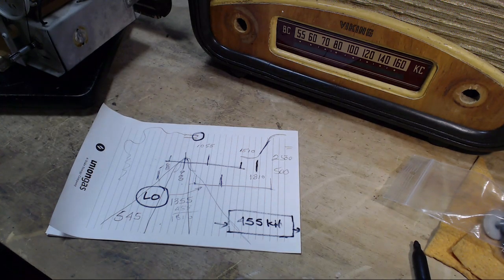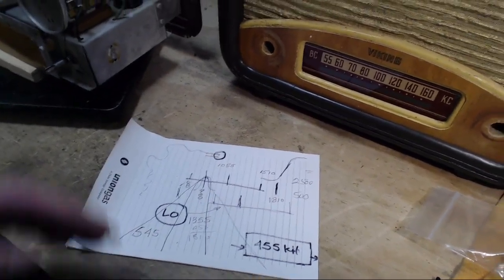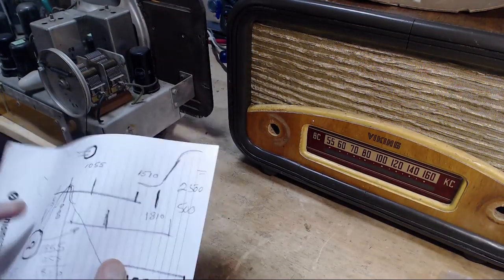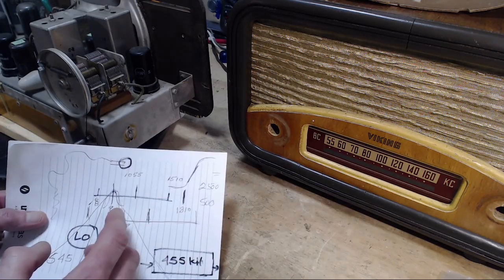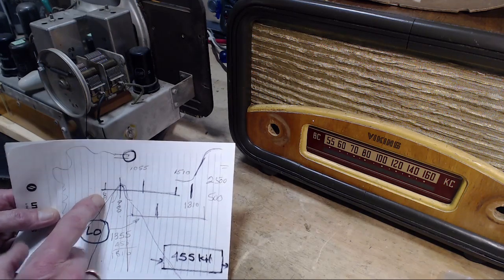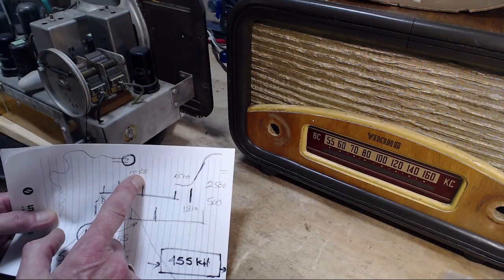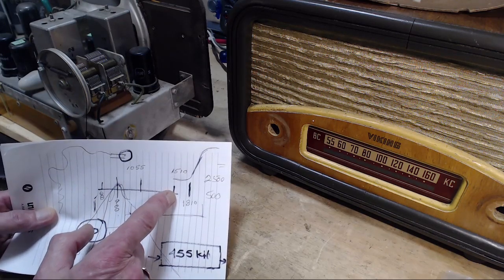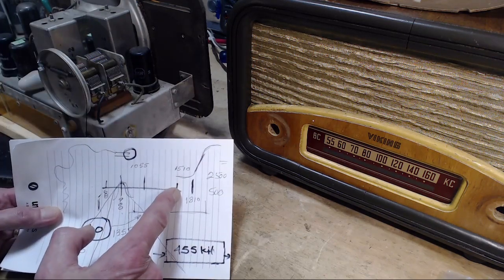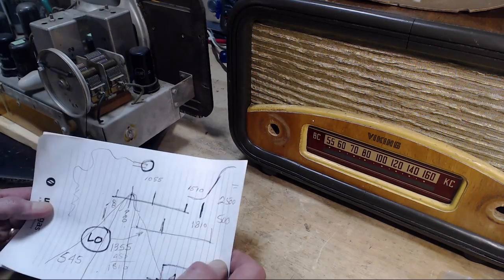Now, if we want to play around with this radio over here, I think I would set up this exact scenario, the one I just talked about. We tune the radio to 600. We know the local oscillator should then be at 1055. And we know the radio is sensitive then to 455 above that, 1510. If I tune the radio to 600 and pump a 1510 signal into the radio, will we hear it? That's basically what it amounts to.